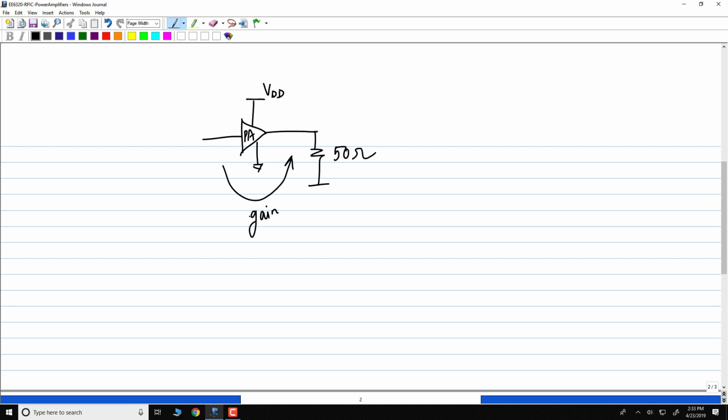But common source is better because the input impedance is, I'll put it in a different way, of course, it's capacitive, right? So you don't put in real power into it. So that is one advantage. The other advantage is, of course, capacitive loads can be easily driven by other CMOS amplifiers. That also you know, right? It is harder to drive a resistive load compared to a capacitive load. Most importantly, it can give you the maximum amount of gain compared to the other two structures. So we will choose the common source amplifier. So let us start with that.